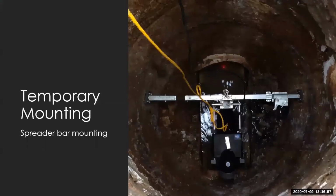Here's another temporary mount, and this one is more of a jack style. Looks like an old jack from a car. There are hydraulic ones out there as well, but this will crank across the manhole and hold that sensor in place. Again, the XY axis, the diagnostics that come with it, is very important in order to know that you have it installed correctly. So this is kind of give you an example of where they would do this. We see these more in like Hobos pipes and things like that, where they don't want to put screws or any kind of bolts into the manhole wall.